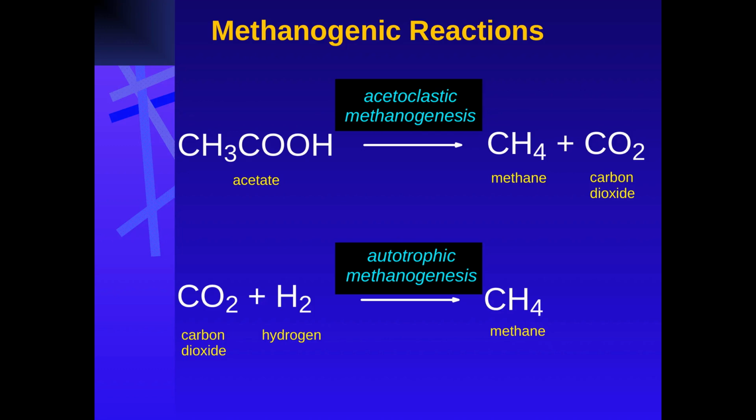The anaerobic filter is one of the earliest high-rate anaerobic systems. It consists of a packed bed of media, such as plastic rings or stones, on which a biofilm of anaerobic microorganisms develops. Wastewater flows upward through the media, and the organic pollutants are converted to biogas. The media provides a large surface area for biomass attachment, preventing it from being washed out of the reactor.